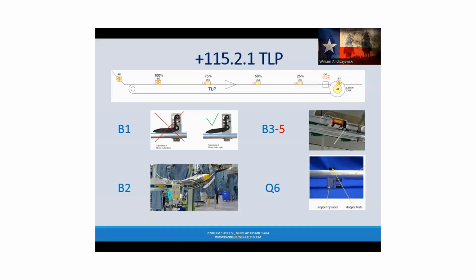Are B's always sensors? These are always going to be sensors. Qs are going to be your solenoid. Qs are also contactors. S's are switches. P's are lights. Those are the most common ones, I think. Right, Mashley? Anything else up there? And motor. And W is usually a cable, like WM.